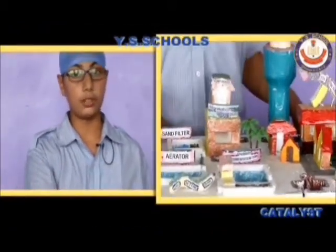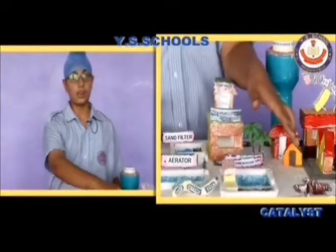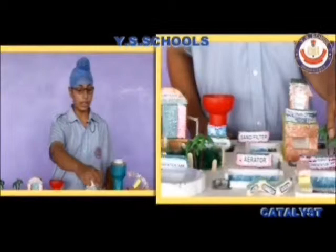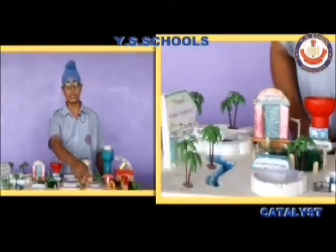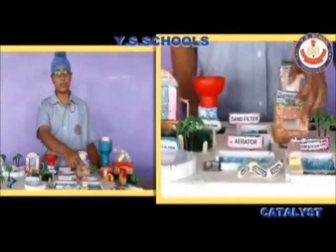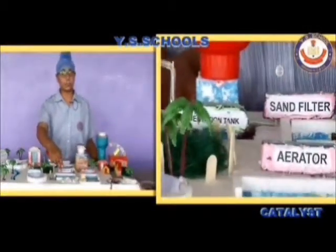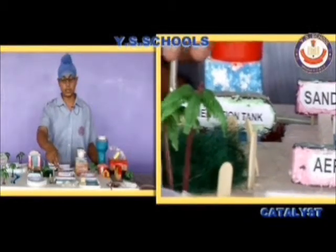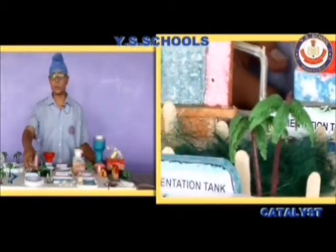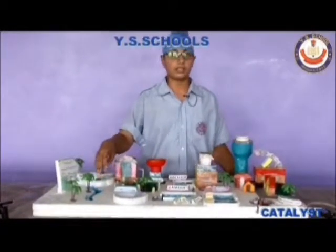Now I will tell you about the sewage system. Sewage passes first through a coarse screening tank where all the bulky material is removed. Then it goes to the grit settling tank where the grit is removed. Then it comes to the primary sedimentation tank which allows fine sludge to settle down. Then the aerator bubbles air through the liquid, which spreads bacteria to break down the sewage. Then the final tank removes any remaining solids. In this method, rivers are also not polluted.